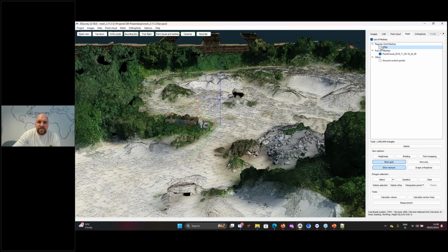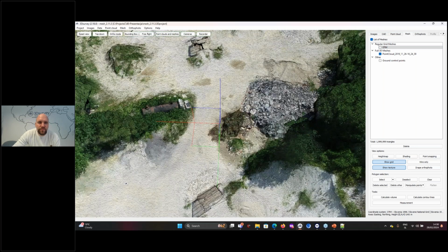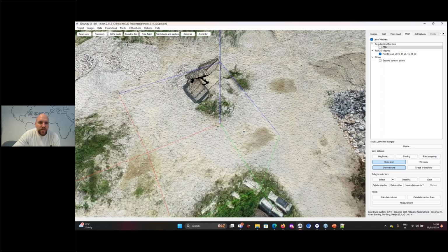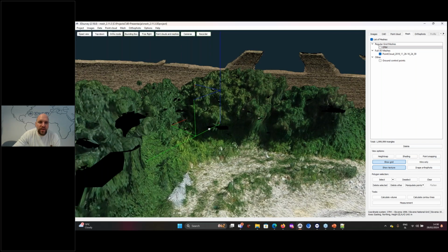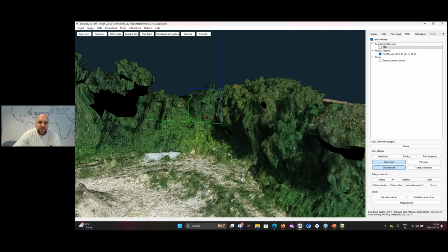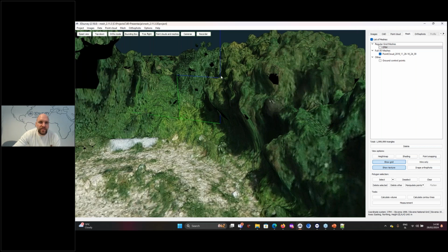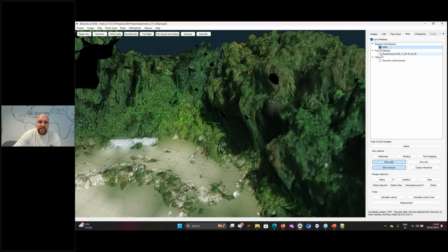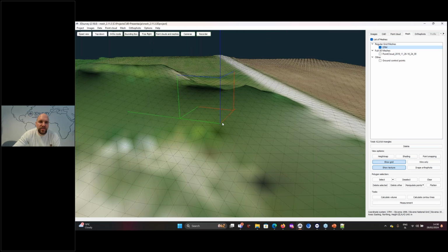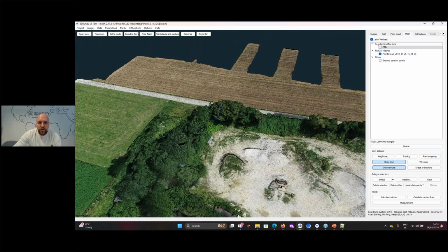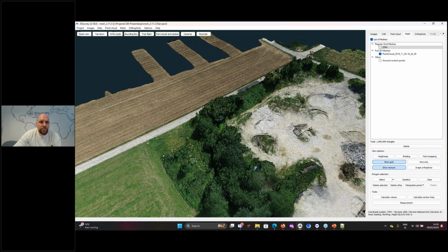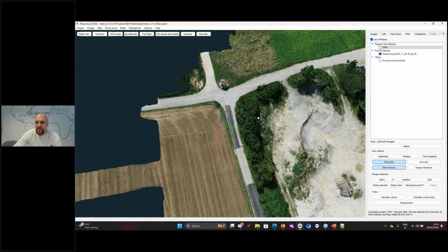The full 3D mesh, on the other hand, is more useful for visualization. It has an irregular network, so for this position here, we can have different elevations for a certain position. Here, where we have a regular grid mesh, this one is more 2.5D. For this point here, only one elevation is possible. We use this for visualization purposes, and we can also draw on it.